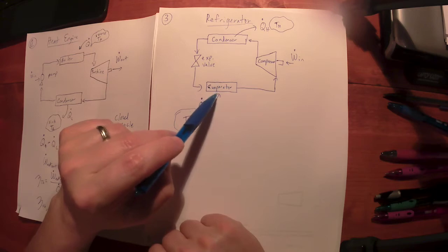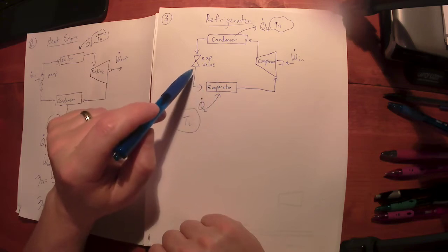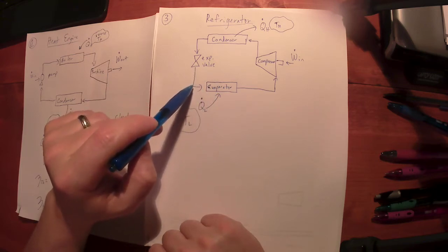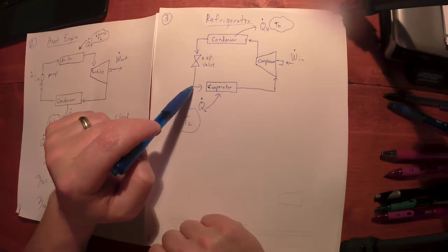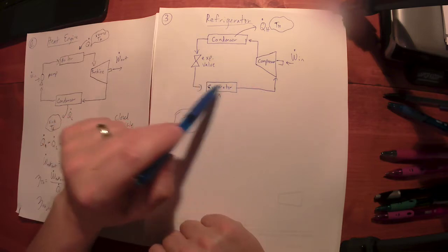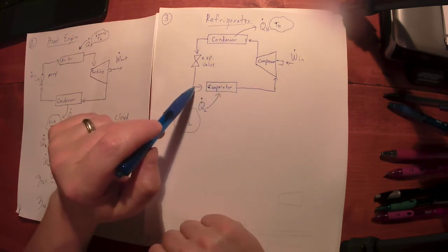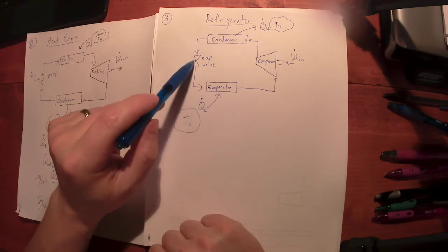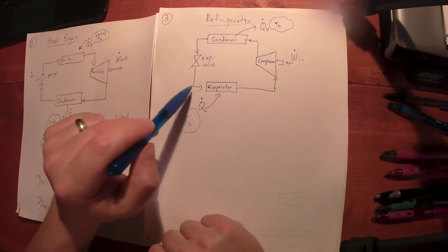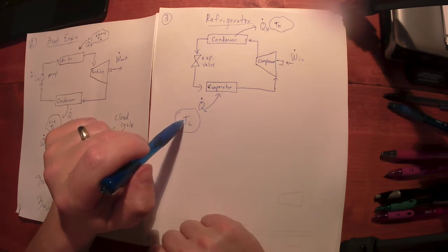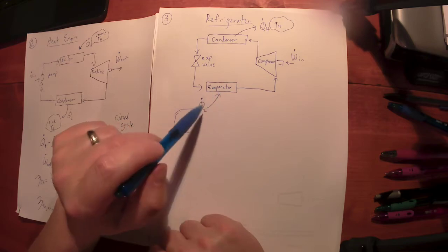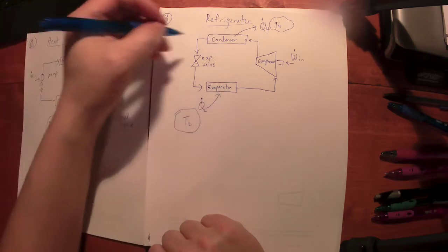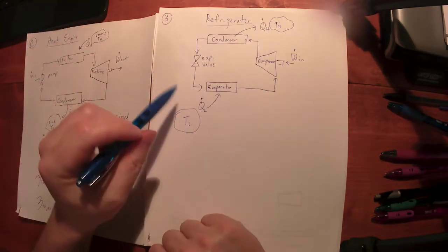So the goal of the evaporator, so basically I'm bringing in typically some kind of a mixture. Maybe it's even all the way down at the liquid phase, but again, I've caused a pressure drop, which also causes a temperature drop in the refrigerant. So this is the low pressure side, and it's the cold side, and I get somehow through the expansion process, I get the temperature to drop. So the refrigerant is now cooler than the cold space, so the refrigerant will absorb heat from this cold space in the evaporator. And then the process is ready to repeat.